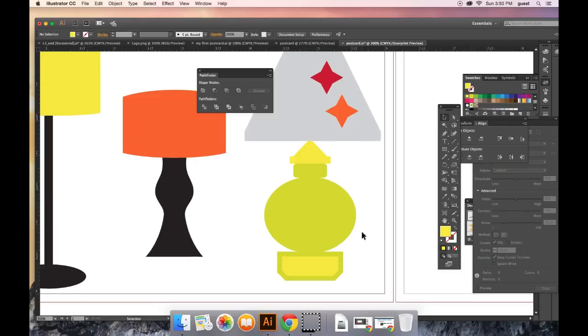And so the first thing we're going to do is we're going to select the rectangle tool, and we are going to draw a rectangle that has a width of 0.5 and also a height of 0.1. And click OK. And there you see we have that rectangle there. And I'm going to move the rectangle so that it intersects right at the bottom here and in the center. Okay. And it looks like it needs to come down just a tad there.